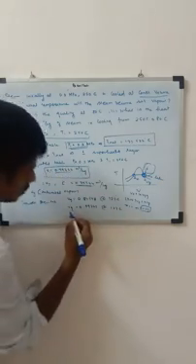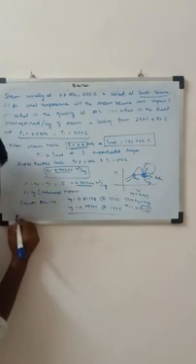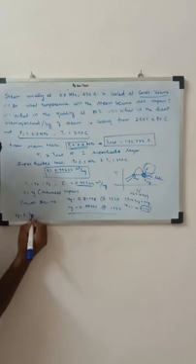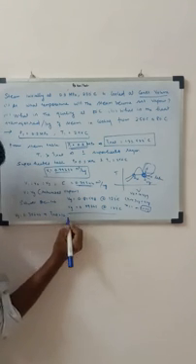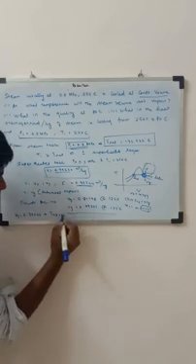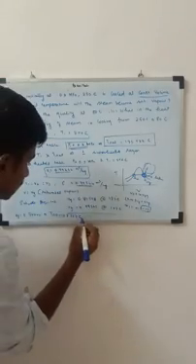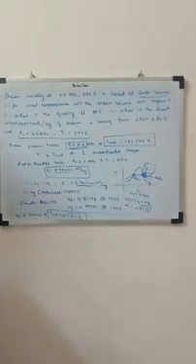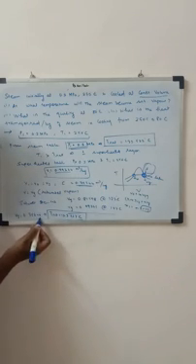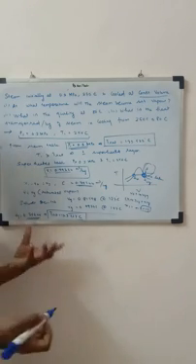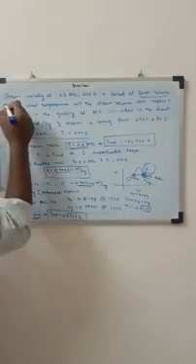So what am I going to do? I am going to just interpolate. For a given value of Vg equal to 0.79644, my temperature is 123.837 degrees. So when I cool down the steam and the temperature reaches 123.837, my volume is equal to Vg. That means it has become the saturated vapor. So this is the temperature at which the steam becomes saturated vapor. That is the first part of the question.